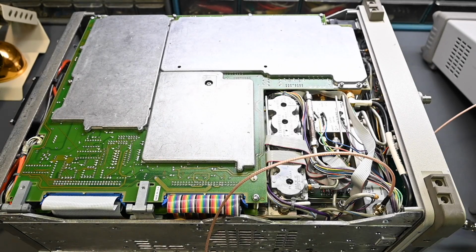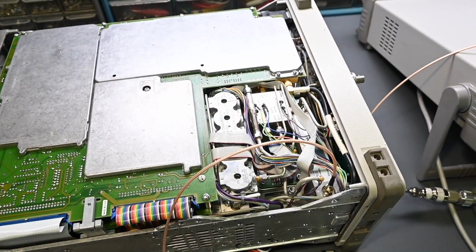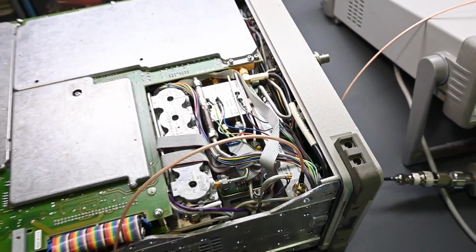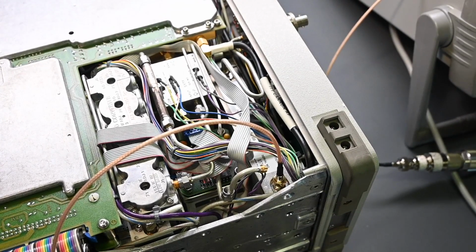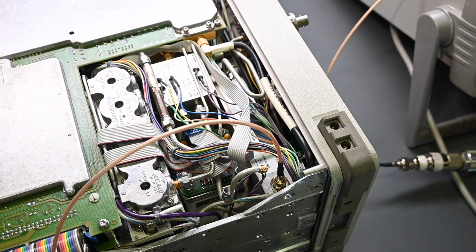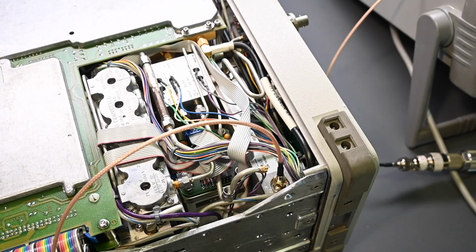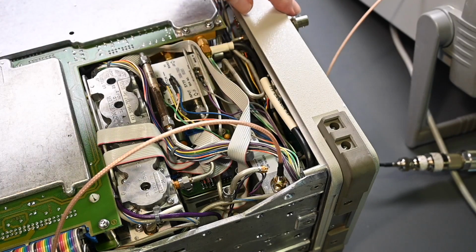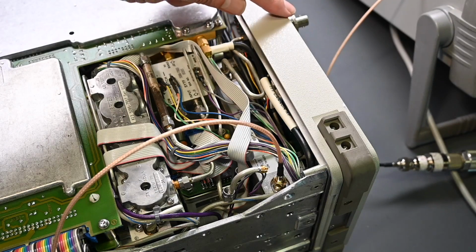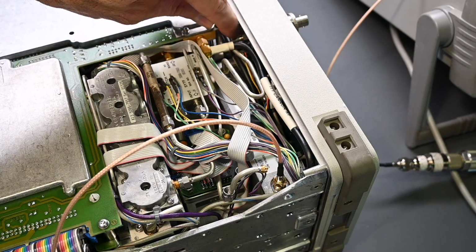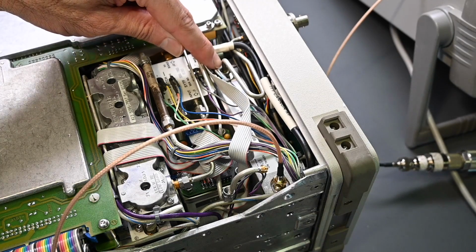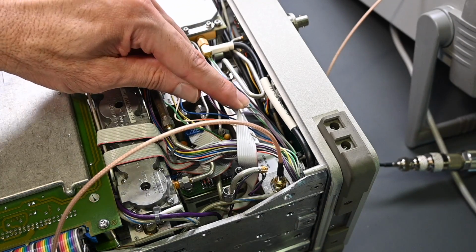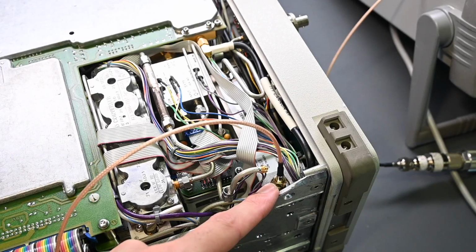So let me get you zoomed in a little bit closer here on the RF attenuator, and you can see a little bit better view from this angle. I'm going to reposition the camera in just a moment when we continue on with the testing, because I can't reach everything the way it's set up here, but this gives a little bit better view down into the spectrum analyzer. So you can see this is the RF input on the front panel. I have an adapter connected as well. On the other side right here, there's a rigid coax that attaches and loops around, comes right here to the input side of the attenuator, and then this is the attenuator down the side, and the output of the attenuator is right over here.